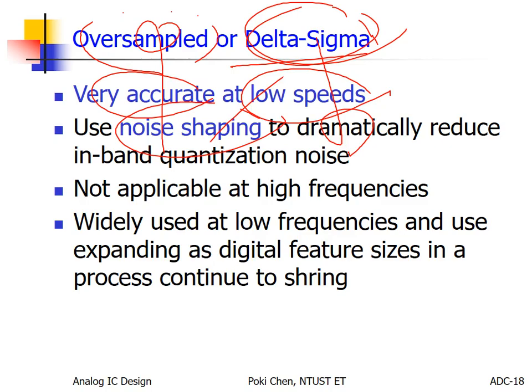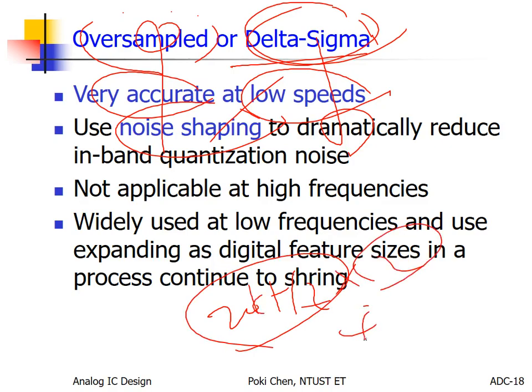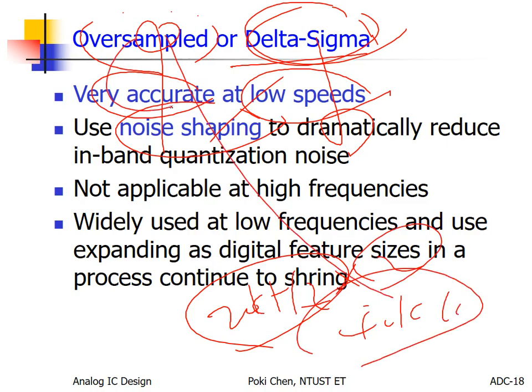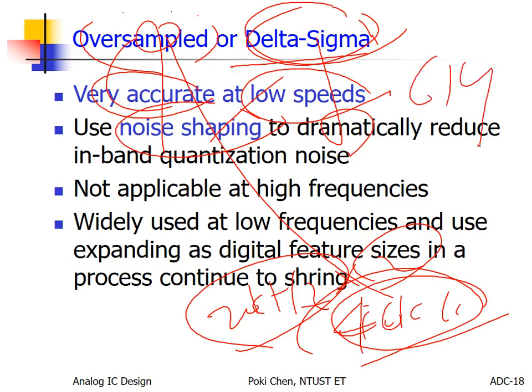Till now, delta sigma is still good for audio signals, not for video. For audio, we only need to handle 20 kilohertz, times 2 for the Nyquist rate, 40 kilohertz. With oversampling, they only need to handle 40 kilohertz in theory. But how about our visual signal? 6 megahertz.